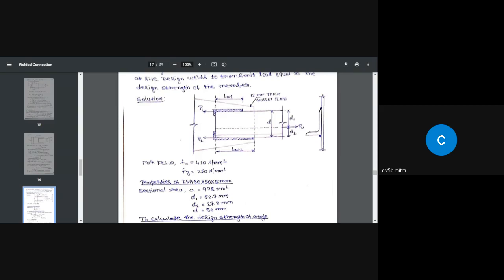So where do we get all those values? For that, please open the steel table. Keep flipping the pages. Of course, first you are going to get rolled steel beams. Further you'll have some more pages. So keep going and stop at page 20 of the steel tables by KLV Ram.